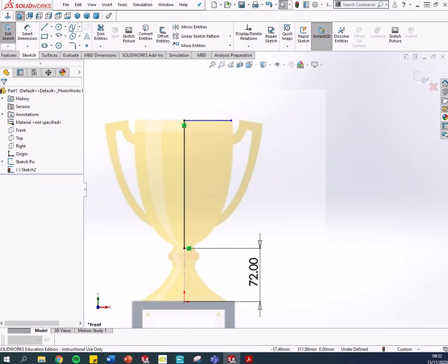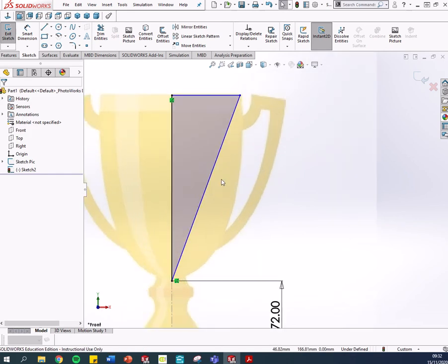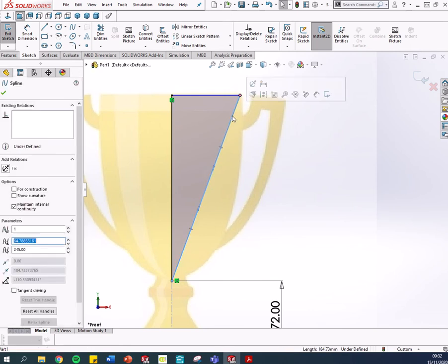What I'm actually going to do is a 2-point spline. And watch this. 1 point, 2 point. Done. Now, that doesn't look very curvy, and it's not, but I can actually manipulate it. If I click on a spline, every point has what's called a spline handle, which consists of a diamond, a triangle, and this little circle.